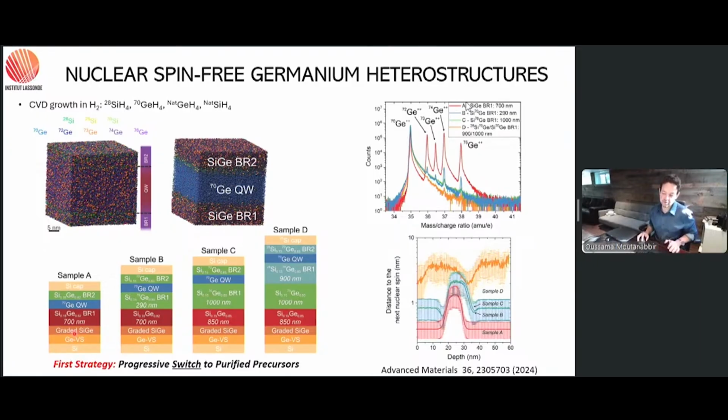And once we grow this germanium layer, we start progressively growing a silicon germanium graded buffer. Basically what we are trying to do is engineer the lattice parameter until we reach the composition that we want. An example here, 18% silicon and 82% germanium. We can keep growing the same structure, and that will give us a fixed surface lattice parameter in which we can build the entire structure. So just to give you an idea, this is typically 2 micron, this is typically another 2 micron, this is about 4 micron. And after that, you add almost 1 micron of relaxed layer.